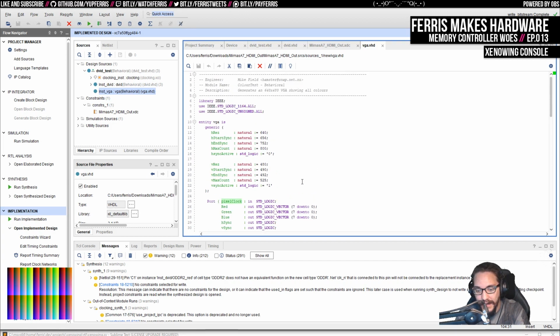And again, need to find out what the memory controller interface that we get is going to be clocked at. Because I don't know how much freedom we're going to have with this board in terms of, can we do a half rate interface? Can we do a quarter rate interface? Because from the example that I saw, we're going to end up running this memory at 400 megahertz. And a half rate interface from that is 200 megahertz, which sounds like a nice speed to target for our system, but I don't even care.